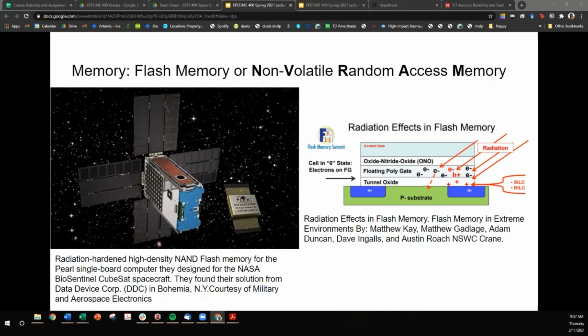Flash memory is typically used to store large amounts of data for startup, like device configuration, calibration tables, boot code, and debug configuration. Flash usually stores software or firmware that is expected to be updated, but otherwise does not change during normal operations. So it's this hybrid of, even when power is off, this kind of memory retains the information, but it has that added advantage that you can update and change this memory. It's not just read-only memory. It has capabilities beyond that.